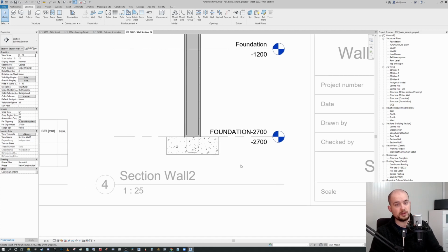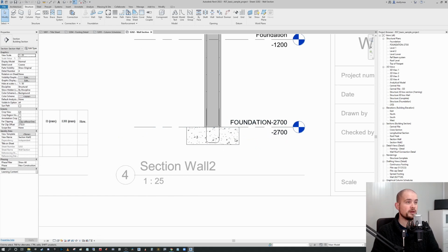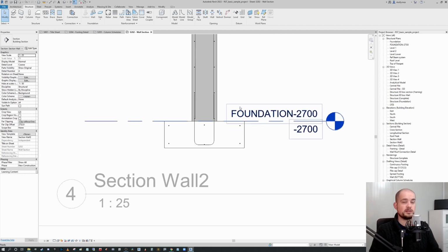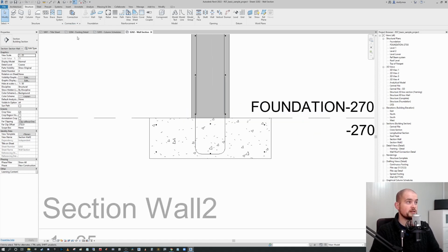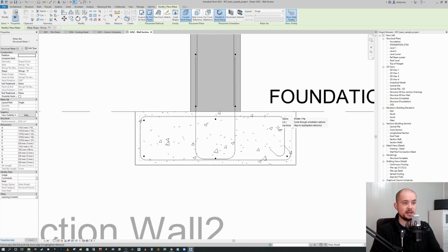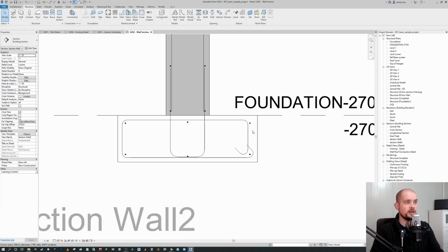The number one feature I think that they've implemented for the rebar is the ability to actually draw 2-point rather than sketch it out. What I mean by that is you can use a rectangular drawing format to place your rebar. So in this instance, for example, if I go to structure, excuse me, rebar, I'm going to select by 2 points, and I'm literally going to click corner to corner there. Now that hasn't coupled properly, but you can see the power of that rather than historically having to go through and sketch the boundary. So that's one way that it has improved dramatically.